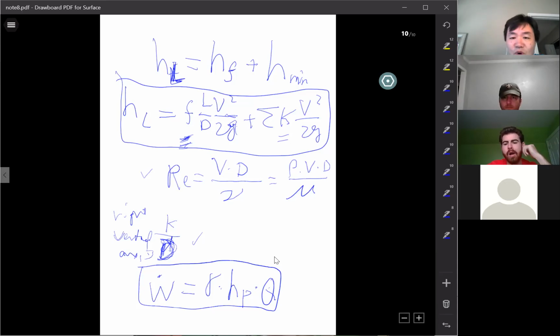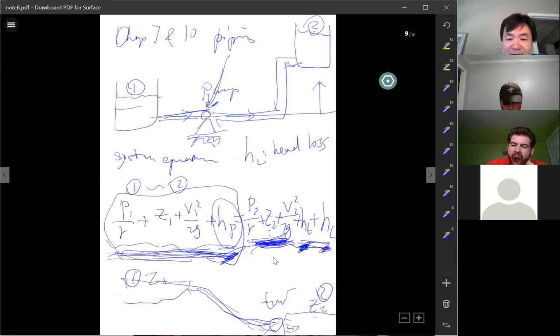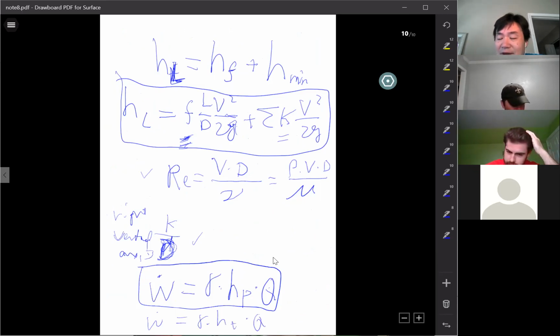These are all the equations in the topic, piping system. I think that's about it. How about the turbine? For the turbine, the same equation applies for turbine power: how much electricity, how much power it can generate. Same thing: gamma times turbine head times flow rate. Again, flow rate is in there. Flow rate matters, how fast the fluid goes. So that's the electric power it can generate.